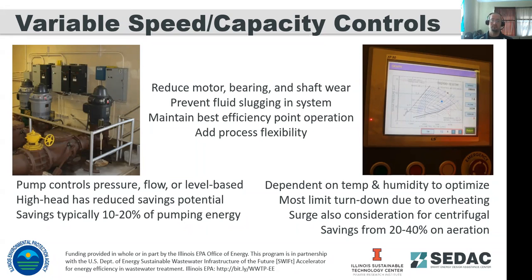On top of that, it reduces motor wear, bearing wear, shaft wear from stop-start operation. It creates excessive heat in the motor, which gradually wears down insulation on the windings. Bearings and shafts from stop-start operation see higher torque, higher loads on those, which increase wear on those over time.